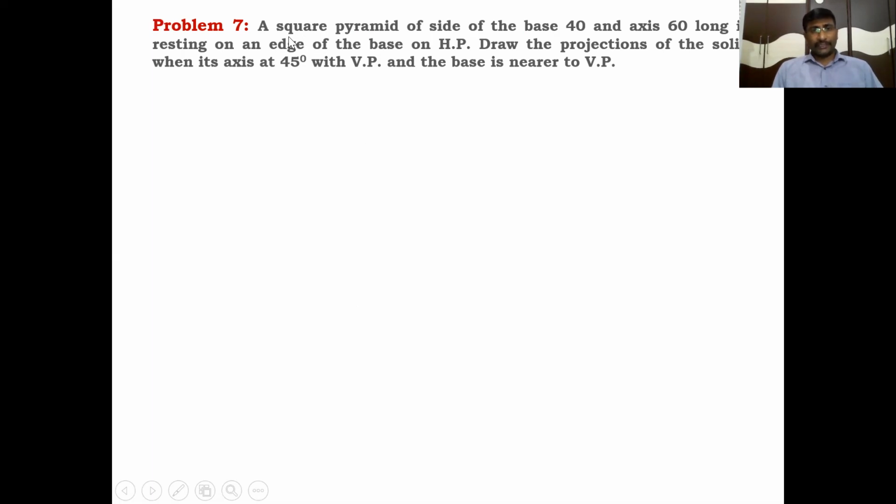While drawing the square, that is the front view, you have to maintain the edge of the base on HP. The edge of the base XY line మీద ఉండే విధంగా draw చేయండి. Okay? First draw the XY line. This is the XY line, on which one edge of the base should lie. This is one of the edges of the square base. Based on this edge, construct a square.